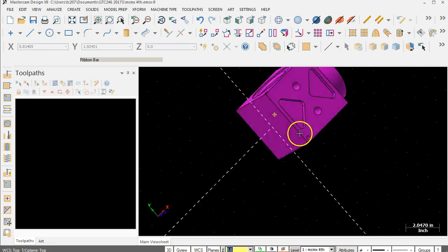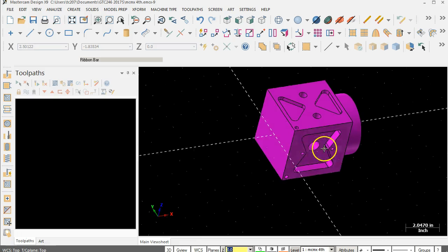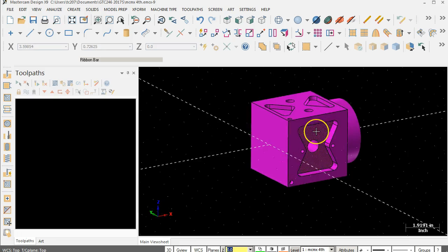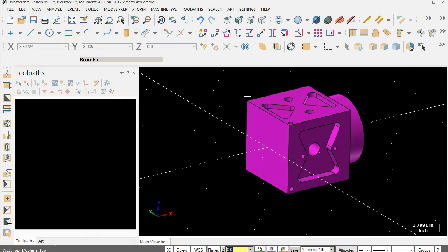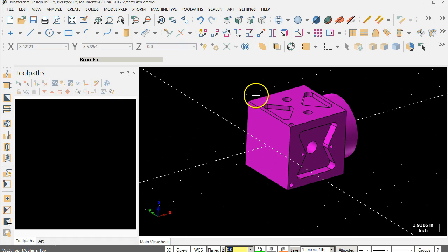One of the things I was thinking of that I didn't do, maybe on one of the next parts, as we accumulate a block of say 4 parts, is putting an angle so that we do have to create an additional plane manager for an orientation that is 45 or 30 degrees off of our axis. Those are going to come up. So keeping this first part kind of simple, we're 90 degrees to the planes, and just going through that initial setup and orientation. We'll see about additional geometry or a compound or a hole coming in at an angle later on.